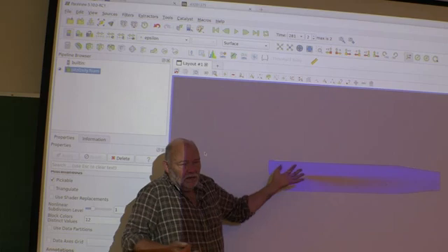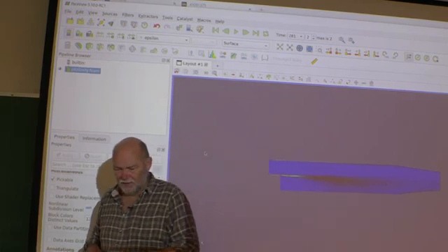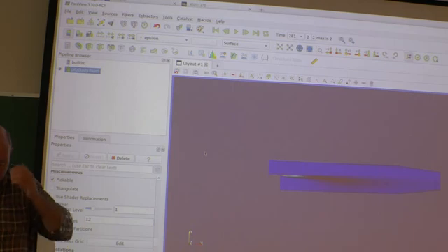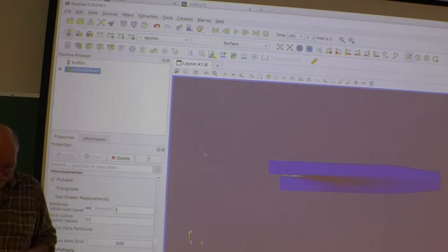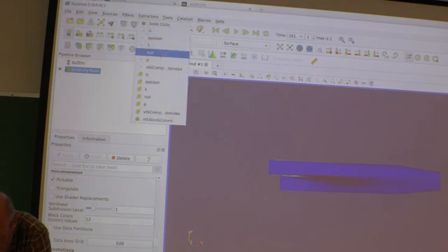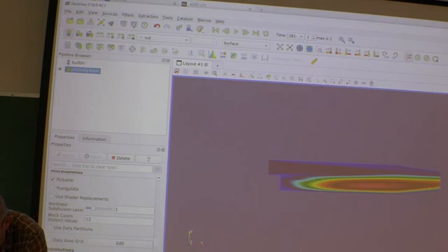Too small, then the turbulence will die. So you have to check the plot so that the inlet doesn't kill your entire simulation. We even have the eddy viscosity, and well, it's quite small actually for this turbulence model.